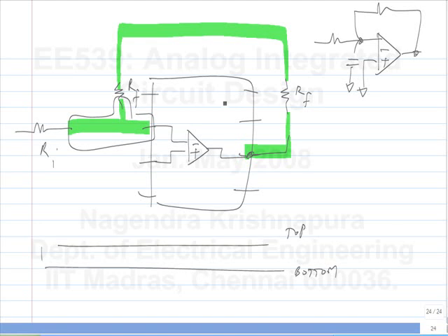Now, if you want a good performance from this type of amplifier, and if you are having trouble with frequency response, what you do is you cut out the copper underneath this. Okay, on the top layer you have this node, whatever this node is. On the bottom layer, and if you have multiple layers of PCB, on all the layers under this, you cut out the copper. Okay, so that you absolutely minimize the capacitance. So these are all the things you have to do.